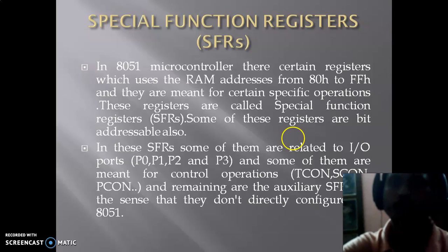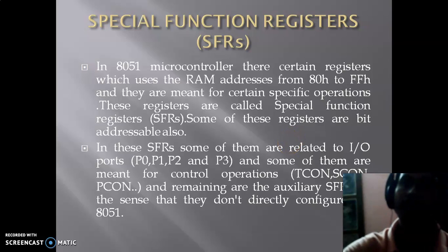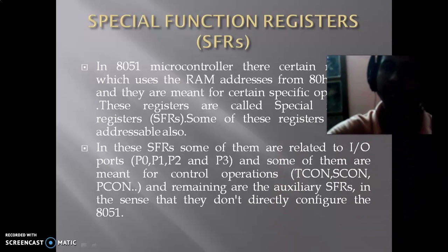Some of the SFRs are IO related ports like P0, P1, P2 and P3. Some are for control operations, like TCON for timer control, SCON for serial communication, and PCON for power control. This kind of special function registers we have, and these are bit addressable also.